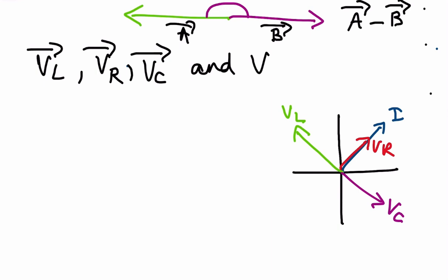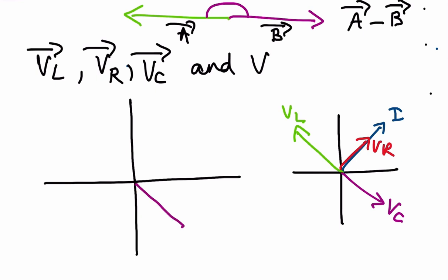Now I will redraw this. The voltage across capacitance and inductance together I have combined. I am drawing like this. That is, in vector form you can write VC bar plus VL bar. Even if you don't write the minus symbol here, no need, because we have taken vector form. In vector form, automatically when you are substituting the values, we will take the negative only.